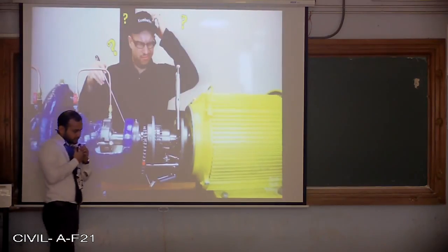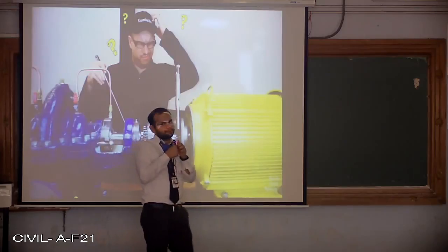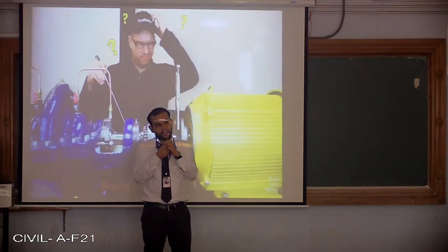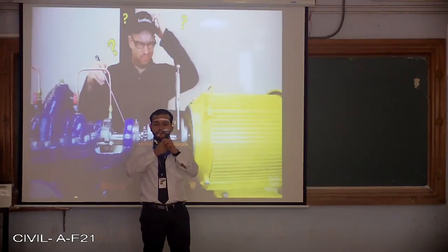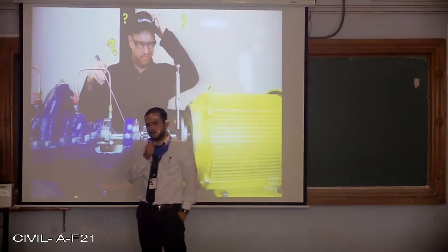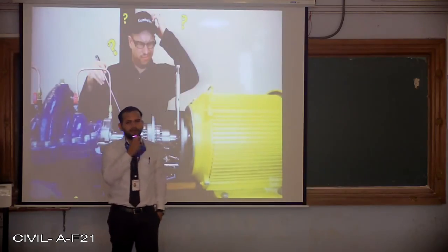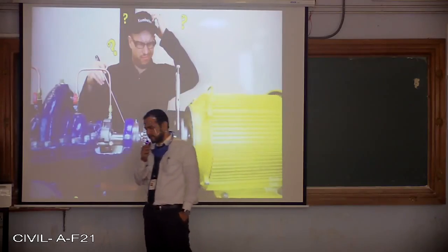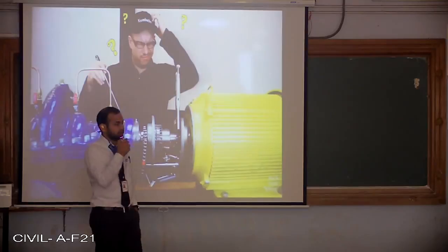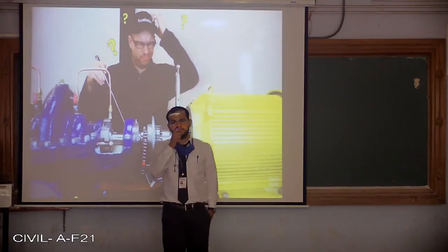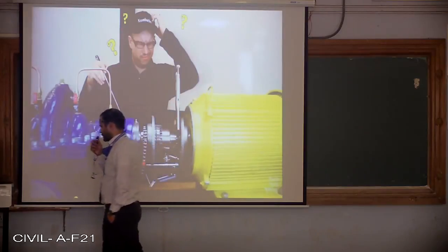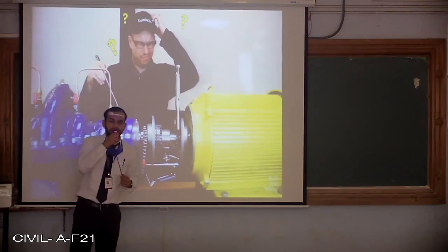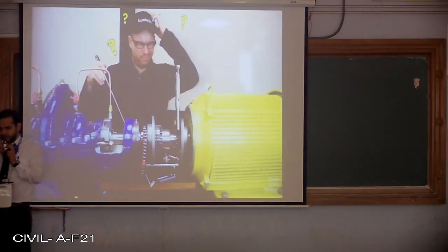So in bigger volumes, you have to have big pumps, and the motor, the shaft, everything has to be aligned. Even in our institute, we have a sewage treatment plant. So we have a rotator there, and if possible, you can go and visit there. So alignment is a very important thing over here. Even if it is slightly misaligned, you may have some big problems occurring over there. So this is what I'm explaining here. Alignment is very important. Even though it's not there in the syllabus, this is just an extra understanding.